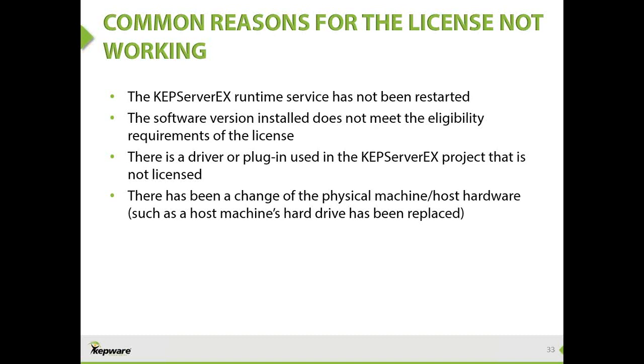The other common reason is you have a driver or plugin that's in use in your KEPServerEX project that's not licensed. Remember, if you say you have the manufacturing suite license, but then you go to use the data logger plugin, if you have manufacturing suite license, but data logger plugin is not, the entire runtime will trigger into demo mode, including all your manufacturing suite items, because the data logger plugin is unlicensed. So you need everything that you're using in your active production project to be licensed.